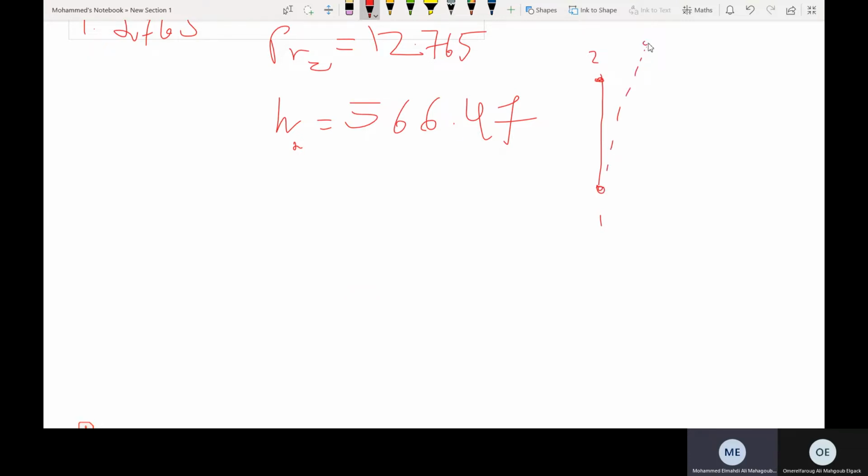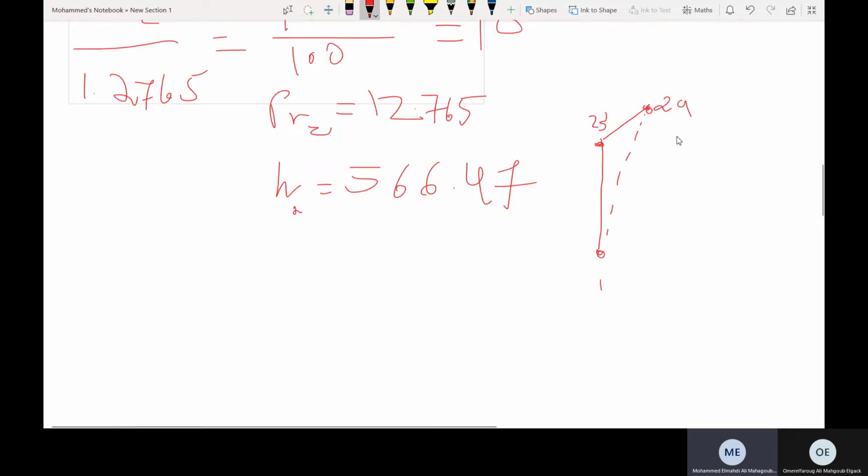With the deviation, this is 2 actual and this is 2 isentropic. What point do we use in calculations of efficiency, heat rejection, work, and these things in the cycle? We always use the actual point, not the isentropic point, remember.